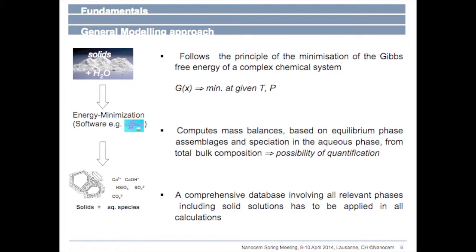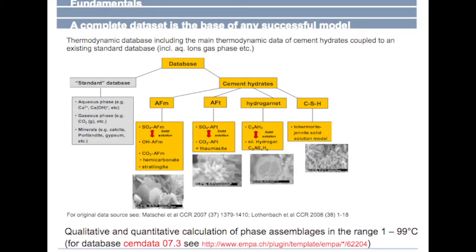Nevertheless, coming now to the application part of these data sets, one example that people may be familiar with, and I think it's quite important also on an industrial scale, is understanding the phase assemblages of hydrated cement. And in the thesis that I did at that time in Core Project 1, one example I found particularly interesting was the impact of carbonate or limestone on cement hydration. What we basically found is that even small amounts of limestone that you can add to your system can change the mineralogy a lot.